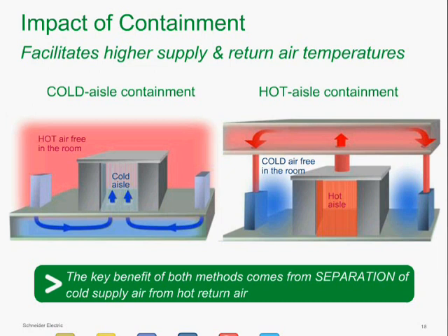If you're retrofitting an existing data center, particularly one with perimeter cooling units, CRACs and CRAHs, then cold aisle containment oftentimes is the best and most flexible choice for deployment. So I would give that to you as a nugget or a general guideline for the practical use of containment systems in the data center.